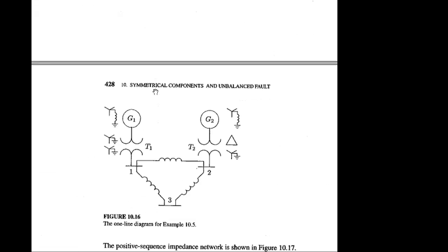You have to put the information for different scenarios. This is the single line diagram, or it might be another single line diagram. Okay, this is the first step to address this type of problem. The first step is to generate the equivalent impedance for all the sequences in terms of the Thevenin concept.